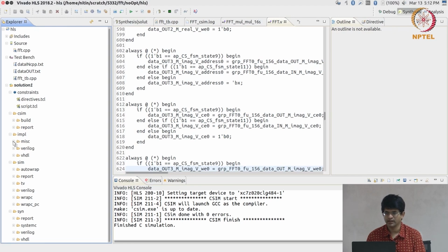What they do provide on the other hand, which is much simpler to implement, is functional equivalence checking. What that means is you already have a test bench, so why not run that same test bench against the generated Verilog code and see whether the same results come out? As you can imagine, that is not bulletproof.